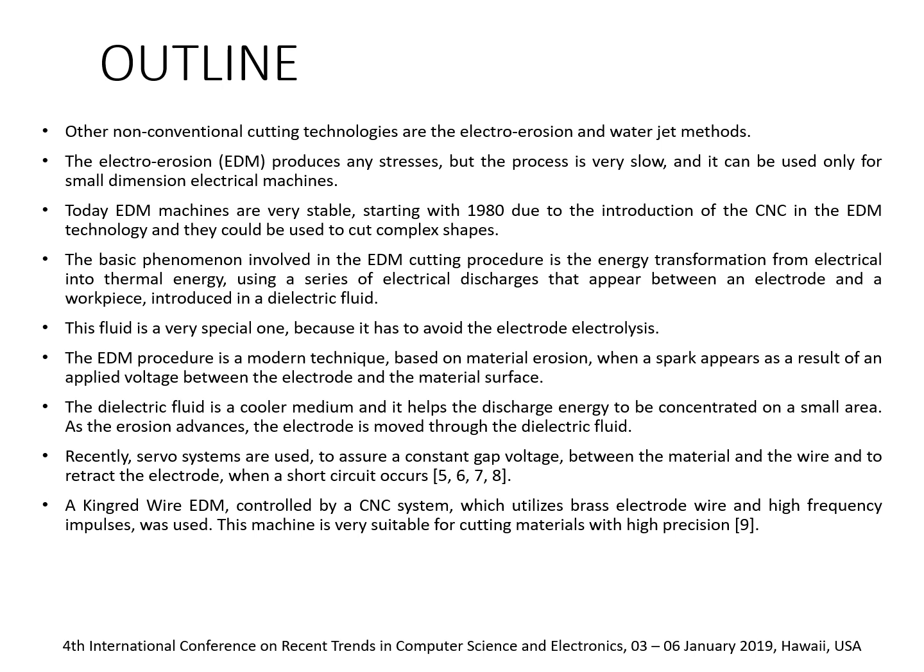The EDM procedure is a modern technique based on material erosion when a spark appears as a result of an applied voltage between the electrode and the material surface. The dielectric fluid is a cooler medium and it helps the discharge energy to be concentrated on a small area. As the erosion advances, the electrode is moved through the dielectric fluid.